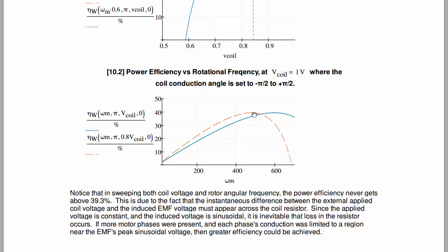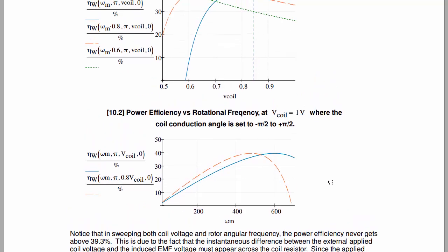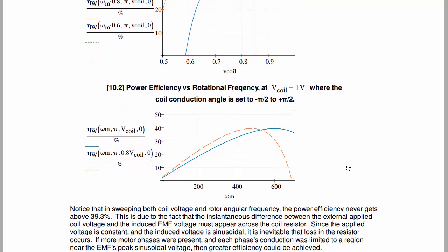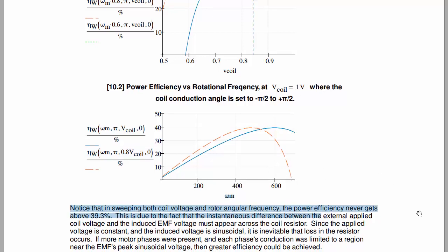And we might ask, well, do we stop there and operate at the maximum efficiency, or do we go beyond the maximum efficiency? And this is all going to depend on how much output power is going out as a function of the angular frequency, and then what is the loss as a function of angular frequency, and those have to meet up. So no, we will not necessarily operate at the maximum efficiency. We might operate below it, we may operate above it. It depends on the lossiness of the system that we are connected to.